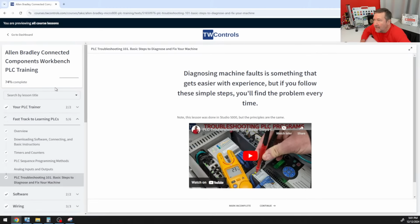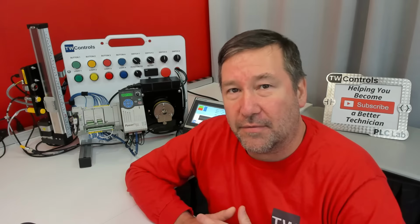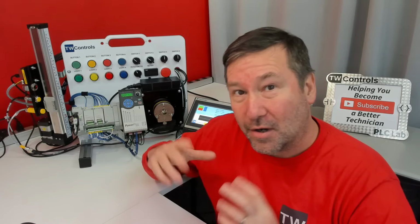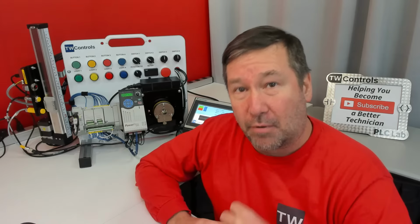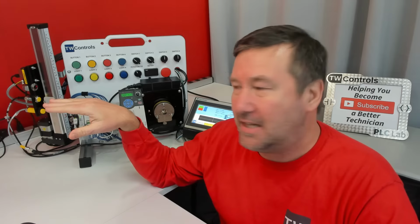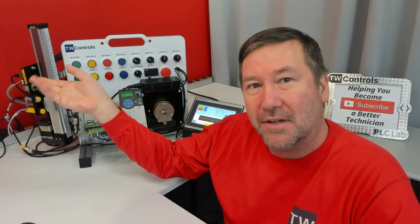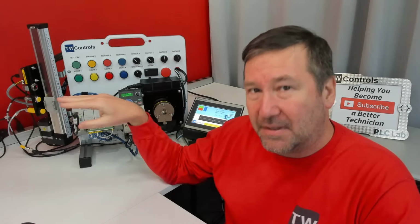The next one that I think a lot of you want to cover is the PID. What I want to do first is prepare our control variable and our process variable. The process variable is that thing out there that we want to be at a certain spot. If it's an oven, maybe the oven's set at 350. So we're going to measure the temperature. That part we're measuring is the process variable. And then we're going to use something to try to get it there. That's the control variable.